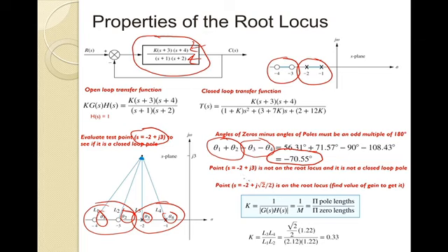So this point here is not shown on the graph. You could certainly sketch it. Find your negative 2 and then your j term root 2 over 2. It would be a little lower than what we're showing here. I'll just randomly draw it somewhere down there. So now we could test, is this point on the root locus? And if so, we could find the value of gain to get it.